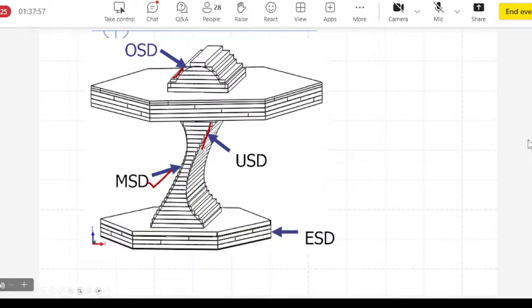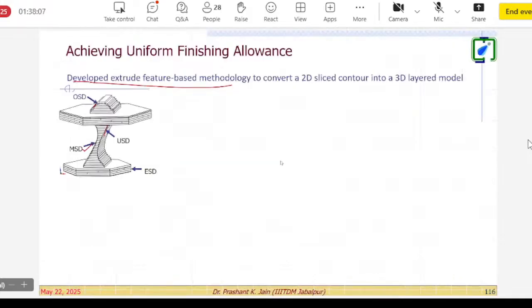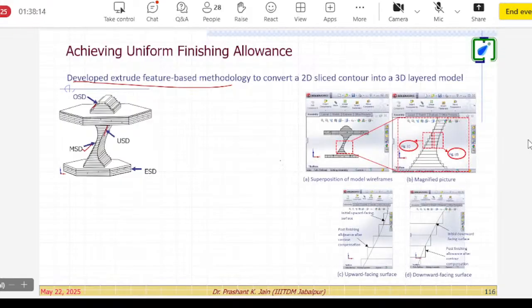Okay. So look at this here, this side, less material, this side, extra material is coming. Mixed type situation is occurring in between this. So we have to find out the solution for this. The algo I have already discussed. How we are implementing, we have taken it to the macro and sliced the entire geometric model, identified the situation and wherever required, we have merged two layers, perform the Boolean operation and then extrude it. So see here, the result is this.